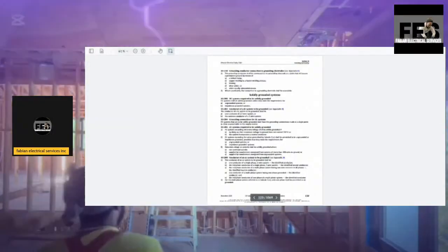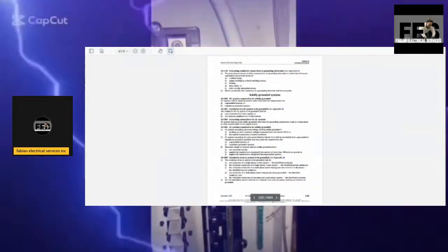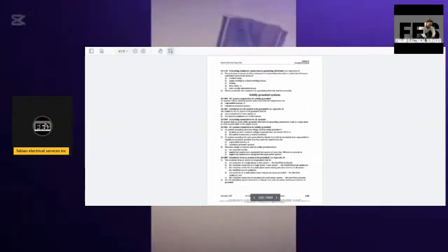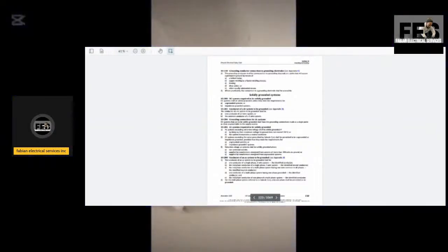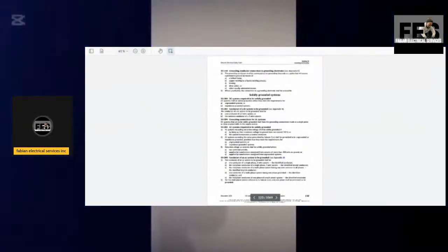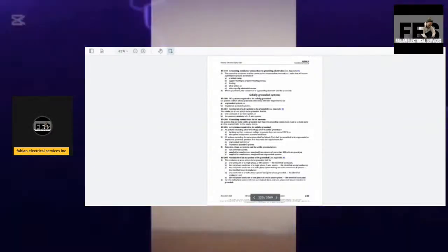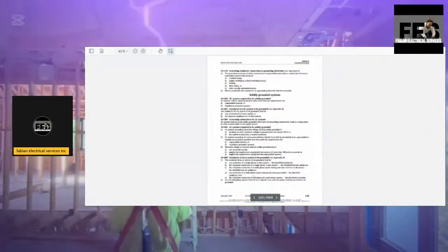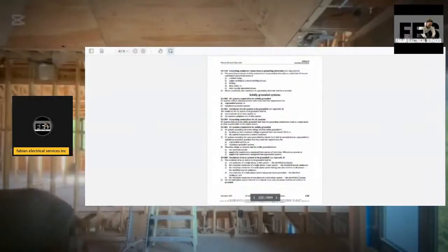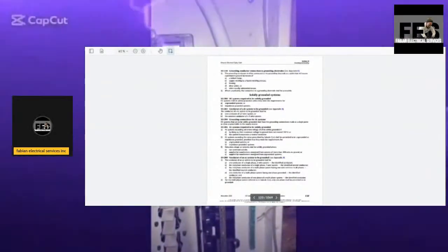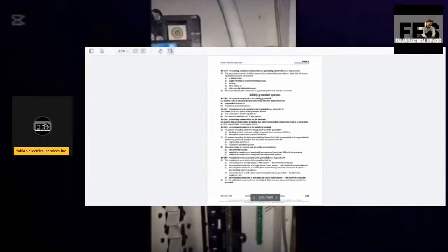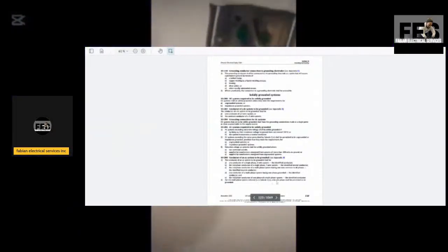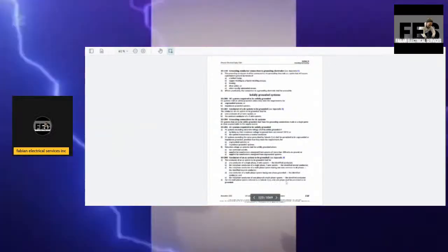Conductors of an AC system to be grounded. The conductors of an AC system to be grounded shall be one conductor of a single-phase two-wire system, the identified conductor; the mid-phase conductor of a single-phase three-wire system, the identified neutral conductor; the mid-phase conductor of a multi-phase system having one wire common to all phases, the identified neutral conductor; one conductor of a multi-phase system having one phase grounded, the identified conductor; and the mid-phase conductor of one phase of a multi-phase system, the identified conductor for the multi-phase system referred to in sub-rule 1. Only one phase shall be permitted to be grounded.